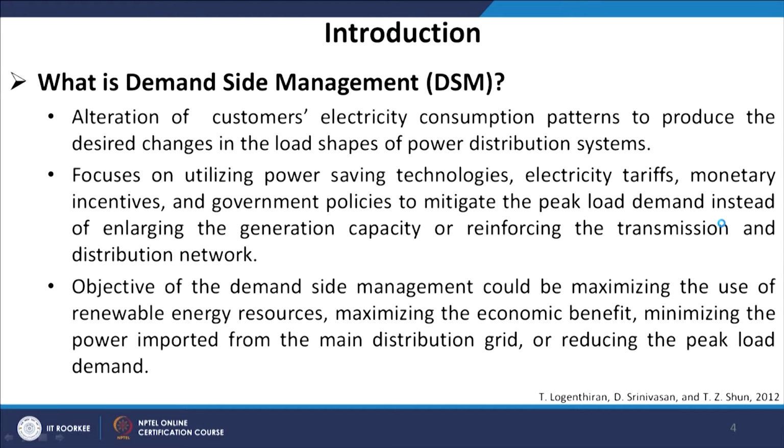Now, I would like to emphasize one thing here: through smart grid programs we can certainly control the generation as well as the loads. In my previous lecture you might have seen, out of 3 loads connected to a DC grid, 2 of them are non-critical and 1 of them is critical. So, if the load is more and the generation is less, then we curtail some of the non-critical loads from the system so that the generation and load can be balanced or matched.